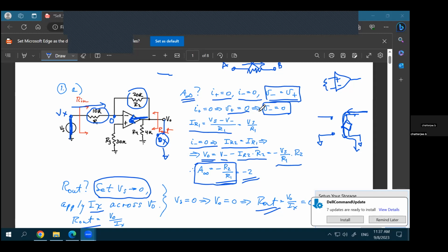It's not a different equation, it's the same equation. And how do you get to the fact that A infinity is 1 upon beta? You divide the numerator and denominator by A beta. So you get 1 upon beta divided by 1 plus 1 upon A beta. Okay, I just need to go back over this here. Then it will be very clear. Just so that you know, all of them are talking about the same equation. It's not a different equation. Okay, thank you.